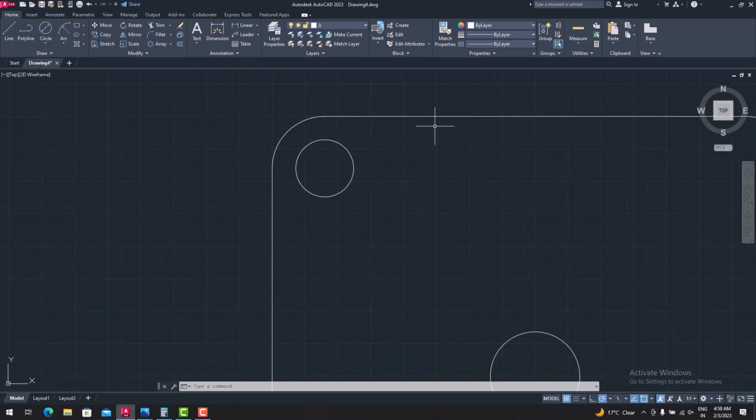All right, now we will create this cutout in the corner side. Now take the polyline and first go to the quadrant point, mark it, and go to the second quadrant point and mark it. Where the two tracking points are colliding, specify that point and specify the sides.